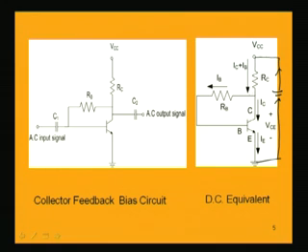One part of this current will flow to the base, that is the base current. The other part will be flowing into the collector, and then this collector current and this base current will meet in the emitter, that will be together flowing, that is summation of this collector and base current, that is equal to the emitter current. So, now if we find out the collector current, then we must first find out the base current, and then we will be finding out by multiplying it with beta. So, what is the base current?